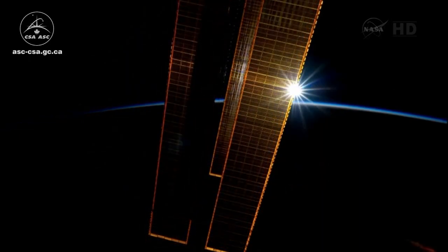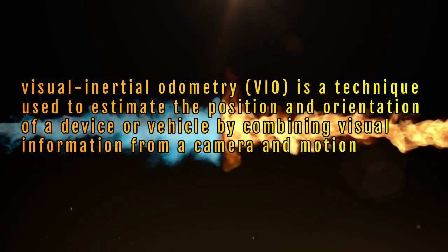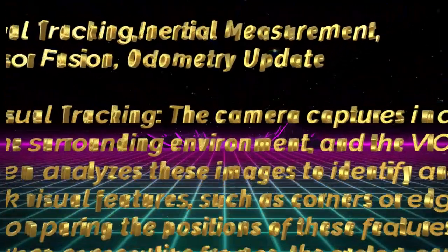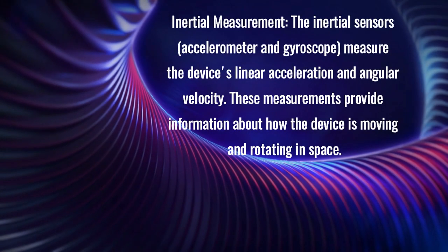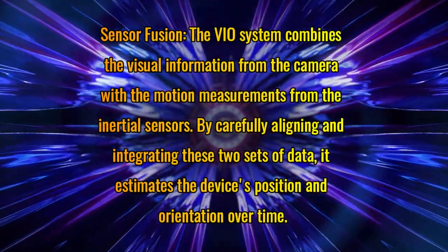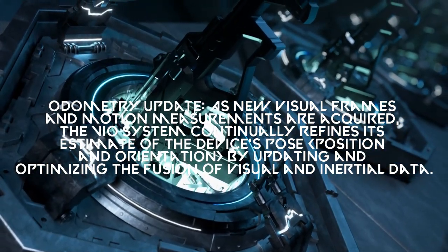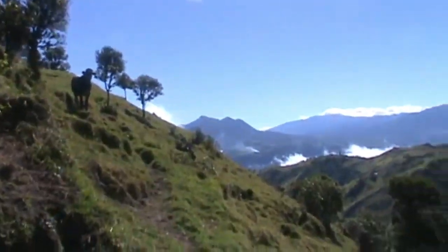Map landmarks that the robot used to orient itself were no longer visible, so it had to rely on visual-inertial odometry to locate its position. Visual-inertial odometry is the process of using sequential camera images to determine the distance traveled. The lack of gravity also makes localization more difficult, as when we are lost here on Earth, for example, we may not immediately know which way is north, but we always know which way is down.